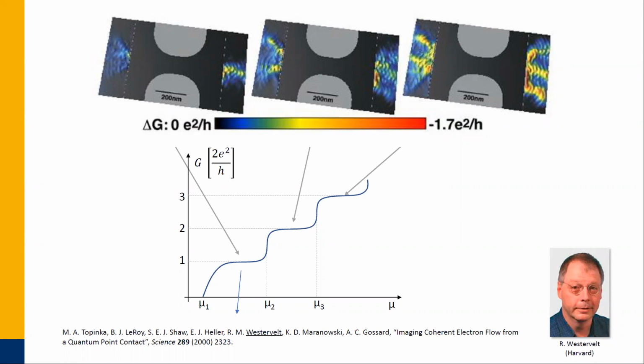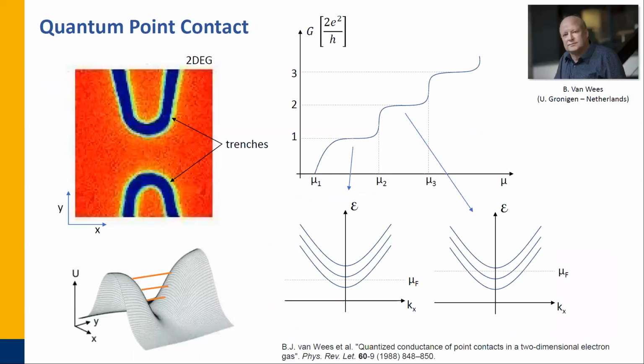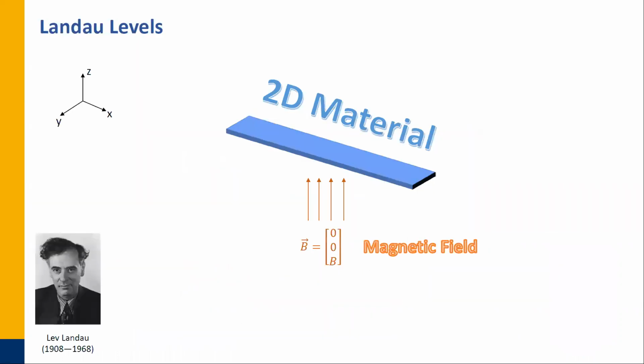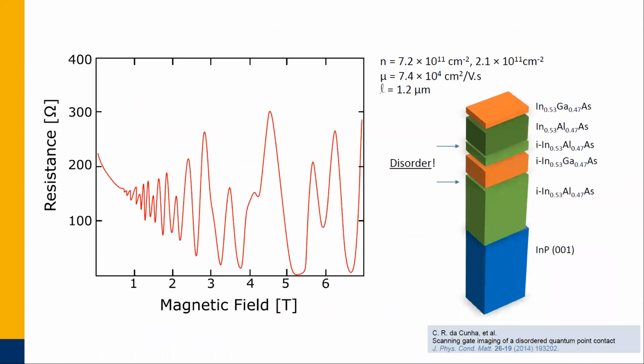No, it's not physically two-dimensional, it's electrically two-dimensional. Physically it's three-dimensional. And there's something that I didn't tell you. If you take the Shubnikov-de Haas measurements here, you see two subbands. So we have the quantum well here, and we have two modes propagating through the quantum well. So it is electrically two-dimensional with two modes propagating. Perfect, the two-dimensional.